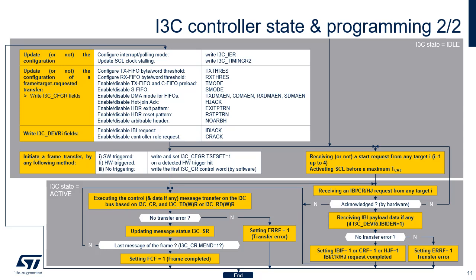In case of target-initiated transfer, the hardware receives and logs the request from the target in its registers, and an event is generated to notify the software on the completion of the frame or on a detected error.